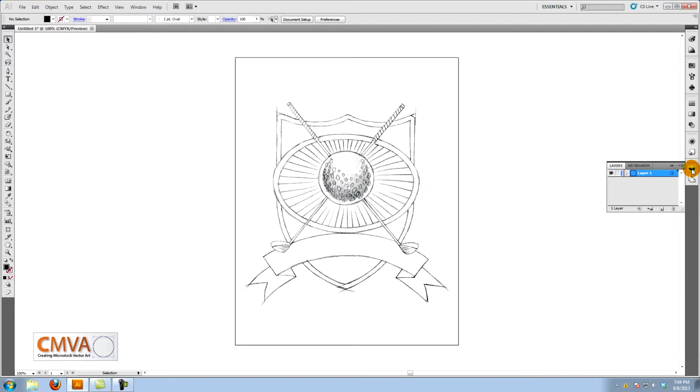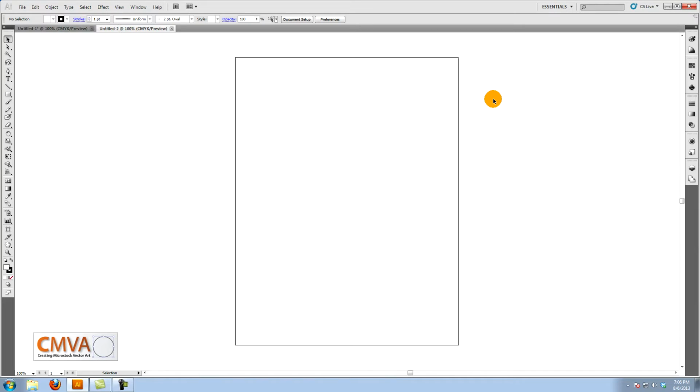Go over to Layers. On the layer with the image, click on the toggles lock to lock that layer and create a new layer. Close the panel. The first object will be the golf ball. First, we need to create the pattern on the surface of the ball. There are different patterns for different manufacturers. This one will use polygon shapes that interlock along the surface.